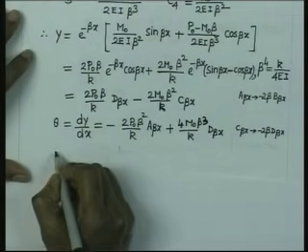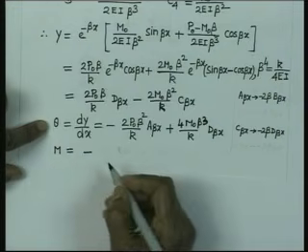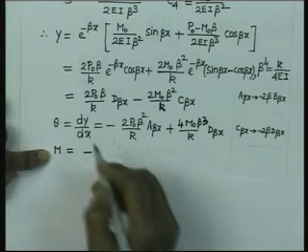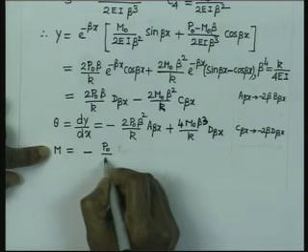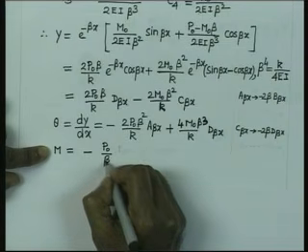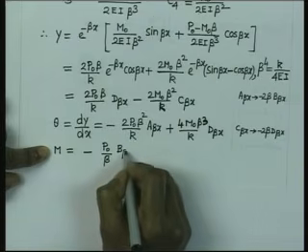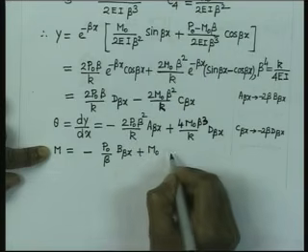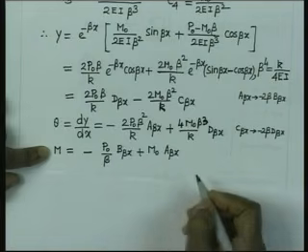Similarly, we can write now M. So, I can take now the double derivative and then write finally the expression for M. M is going to be P0 by beta, this A beta on differentiation will become D beta x plus M0, D on differentiation will become A beta x.